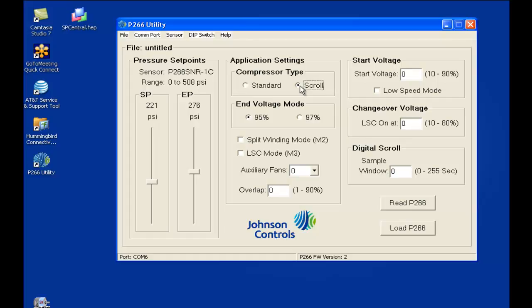You will also need to select the frequency cycle for the compressor. Digital scroll compressors cycle on and off when in operation, usually in intervals up to 4 times per minute. During this cycle, the compressor achieves a high pressure point. The purpose of the selection range is to set an interval which will allow the compressor to reach the maximum pressure. If the interval is too short, this may cause the condenser fans to oscillate.